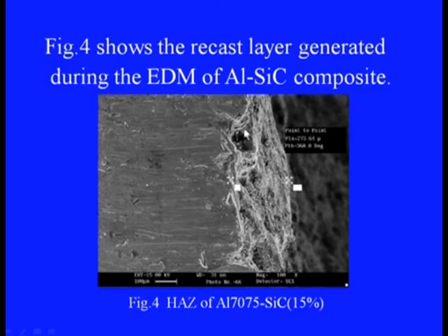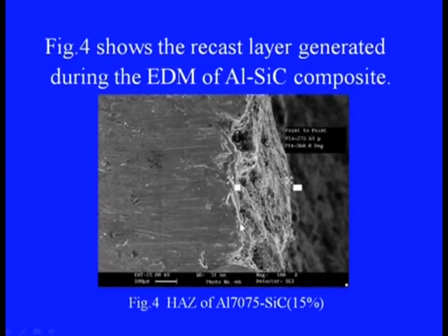And there are certain flaws, porosities, or in some cases some cracks, like micro cracks we can see here on the screen itself. Those are also present in this. Therefore, once this machined workpiece is put into service, there is a possibility that the part may fail through this zone, which is not acceptable. Therefore, in general, if the part is going for a critical use, then this white layer needs to be machined out or removed by using some secondary processes.